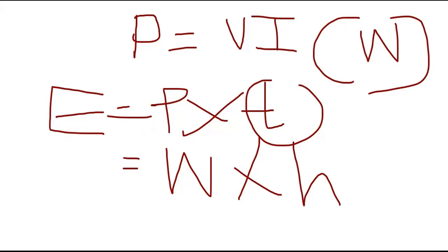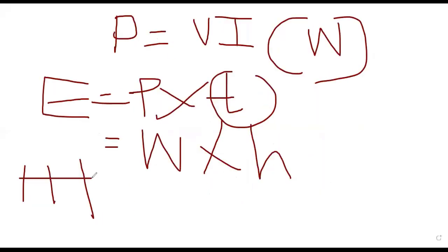So if you remember from our table also, the load analysis table, we ended up having our daily energy to be what? VAH. You remember, after we have included the surge and everything, we had VAH as our daily energy from the table. So this is almost the same, but for the battery, we are using watt hour.